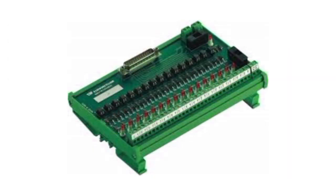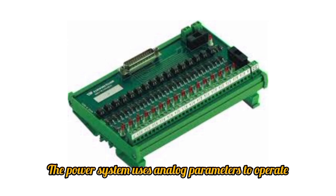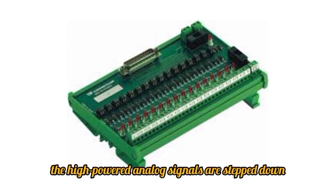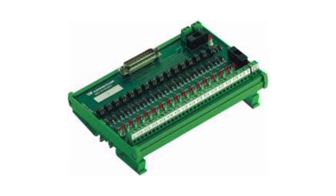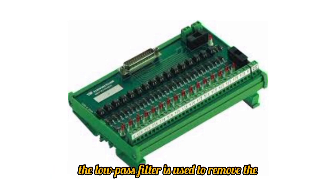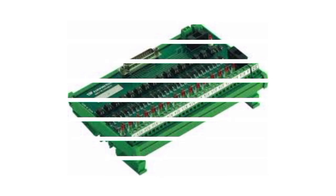Input module. The power system uses analog parameters to operate. With current transformers and voltage transformers, the high-powered analog signals are stepped down. Using low-pass filters, they are fed to the numerical relay. Owing to the corona or induction effect from a nearby high-voltage line, the low-pass filter is used to remove the noisy signal in the device.